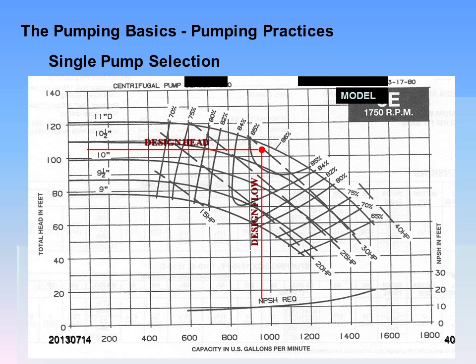We're in the most efficient part of the pump performance. You have about 85%. Here we see our impeller size would be 10.875 based on where we were precisely, but we might go with something different and let the VFD do the work.